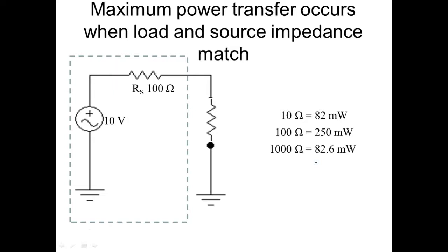So that's impedance matching. That's pretty neat, right? So we understand that. So now these cables. When I deal with these communication cables, guys, you got to be real careful with how much you untwist that cable. I've seen people untwist a lot of that cable to make it easier to terminate. But what did they just do? They changed the impedance of the cable. Now the system can't communicate at its rated frequency.